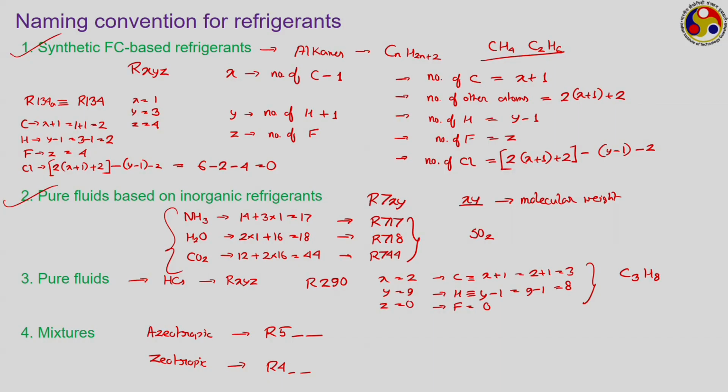And one big problem that we have is when we have to deal with a very large temperature difference between the evaporator and condenser, because we know that as the condenser temperature increases, the COP decreases. Similarly, as the evaporator temperature decreases, the COP also decreases. Now, the condenser temperature generally is fixed by atmospheric considerations, but if we are looking to refrigerate something at very low temperatures, that is, your evaporator temperature is too low, then if we use just the normal cycle, your COP will be extremely low, and therefore, we may have to go for several kinds of modification,